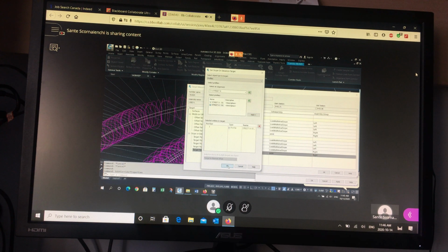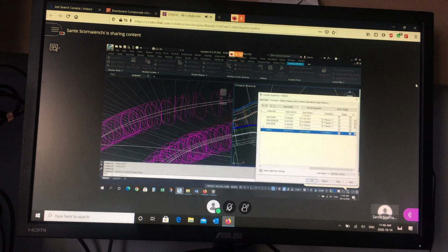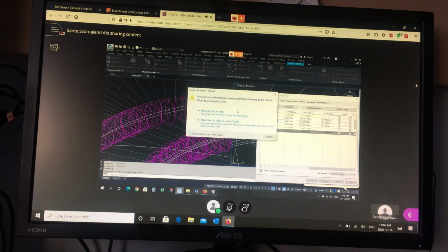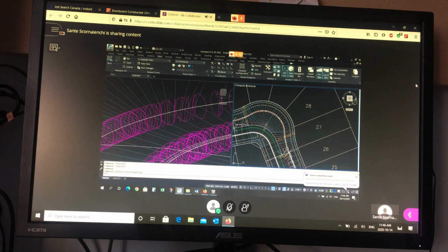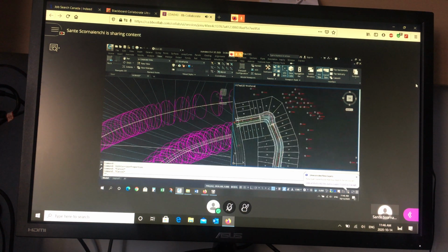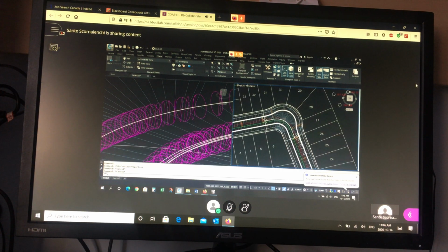Say okay. Watch what happens right here in this left side. The gap is going to be closed. That top white line is going to come down to match the bottom one. Watch. Rebuild. And now the elevations are the same. So what I've done is called targeting. It's going to horizontally go to the position of the center line and vertically match the design elevation at the center line. And now it gives you a final model of the pavement.